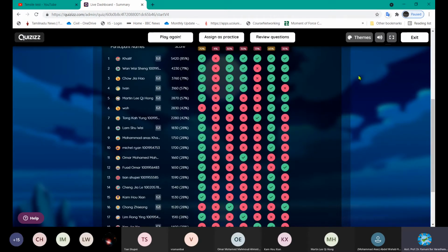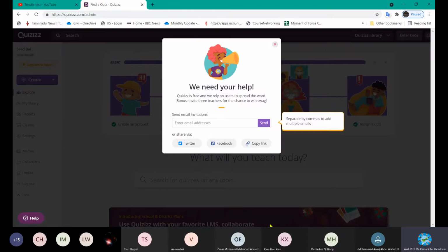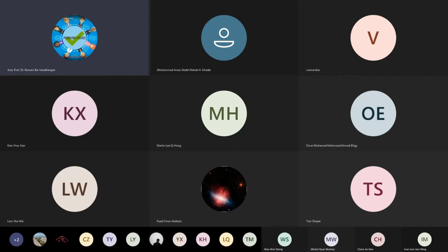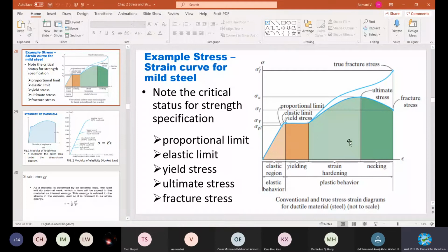Okay, I stop here. We will continue with our class on strain, how to calculate the strain. We saw the stress-strain relationship, which is a material property, right? A material property with which we can say when the material is going to fail. We started with three types of deformation: tensile, compressive, and shear. We took only tensile last time. We conducted a tensile test and found the value of strain through the graphical representation.